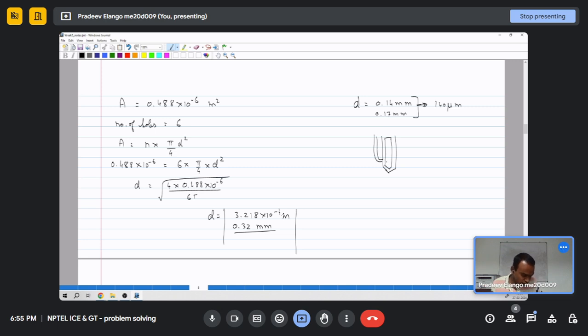Okay, there will be holes here. Once the needle is lifted, fuel flows in and then comes out through these orifice holes. So this hole, where the fuel gets injected from the injector to the cylinder, is called the orifice.